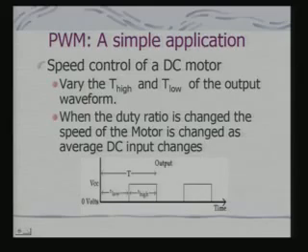This is a very simple way by which I can directly use the PIC microcontroller for DC motor speed control applications. It can be used for a variety of other applications, as I have already told you, intensity control of a light source, temperature control of a heating element, and so on. In fact, one of the major applications for which PIC was designed was control applications, and that is one of the reasons why you have the CCP module on the chip of PIC.